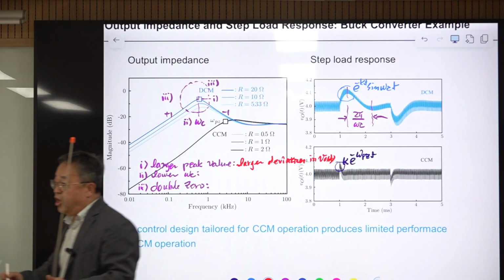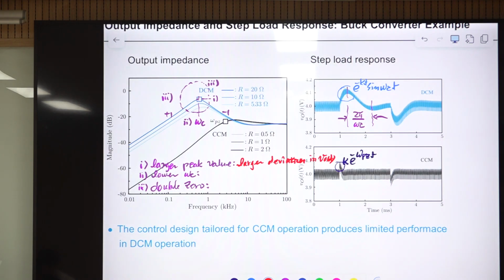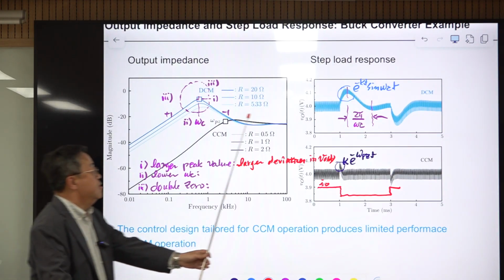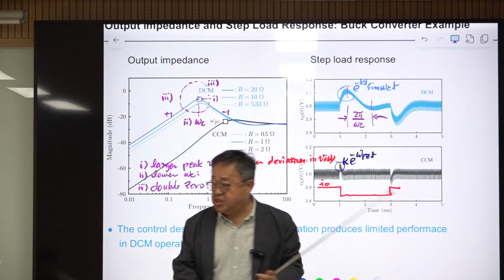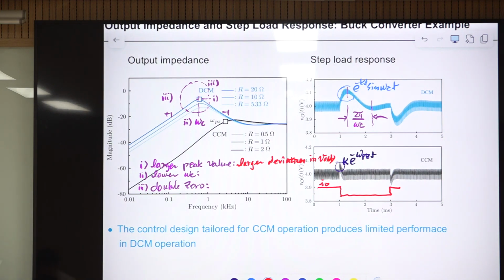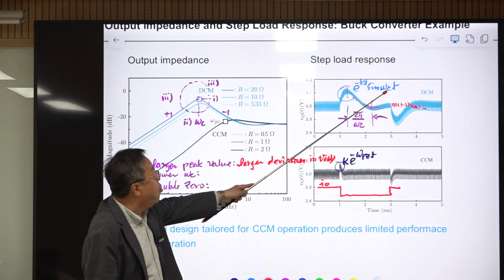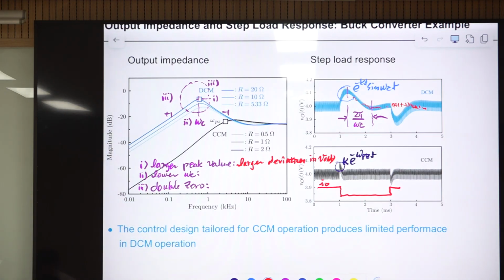So the load change is occurring in this manner. This load current is decreased here and increased here. This is a variation of I/O. If you removed this, then this response will go like this. It will generate this sinusoidal oscillation. And the double pole sinusoidal oscillation frequency is this one, omega c. So because of the presence of this double pole, the response becomes very slow.